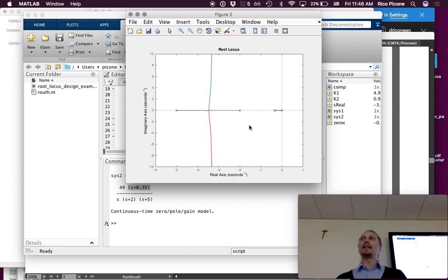But if we had a settling time that was specified to be something that we couldn't affect at all, this would be kind of an issue because what is the effect on settling time of pulling the root locus a little bit to the right? Is it going to be slower or faster? If we pull it to the right, it's going to be a little bit slower.